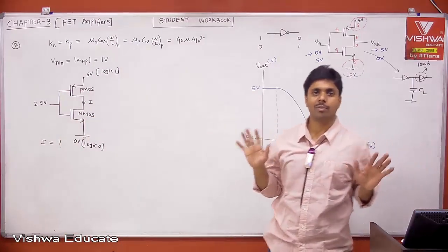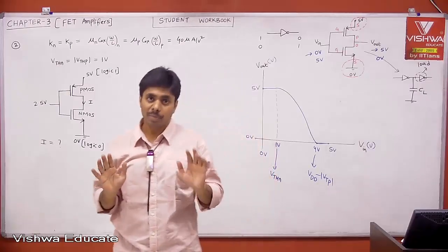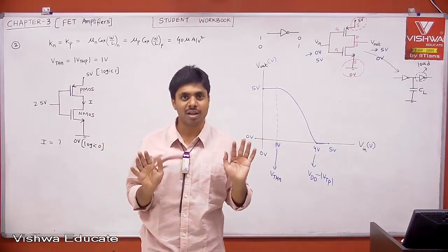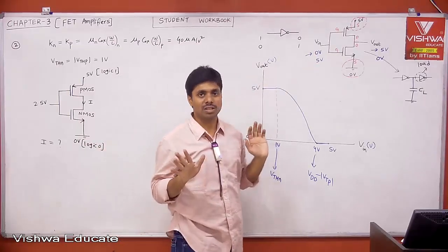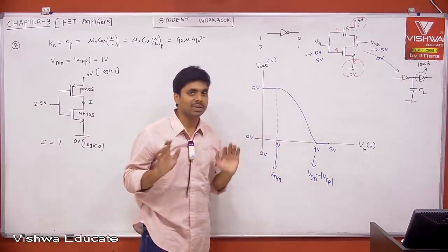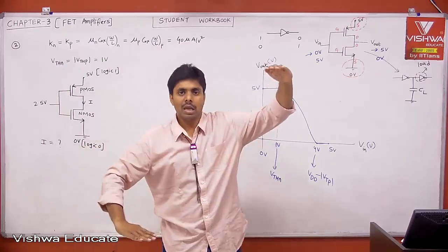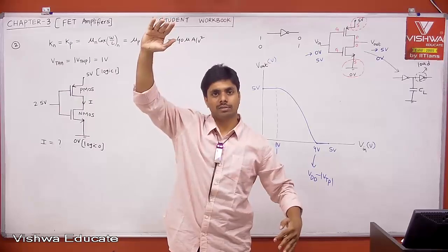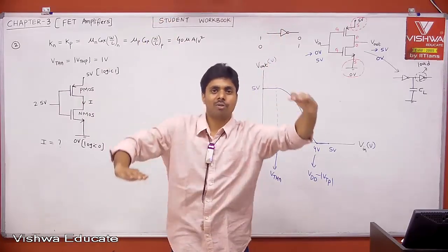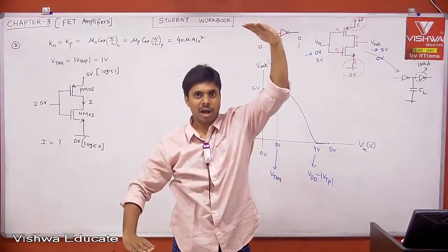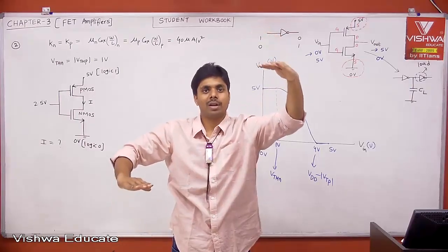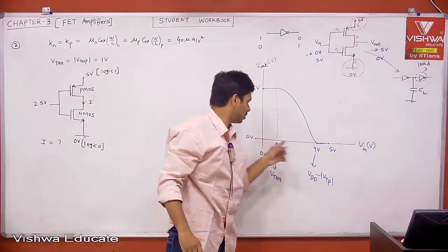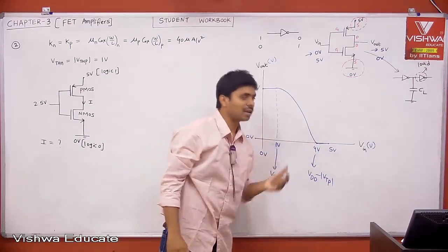I hope everybody understood it. I explained qualitatively, but there are quantitative problems we are going to solve later, meaning what's happening in between for different voltages. But remember, this is our transfer characteristics. Input is 0, output is 1. Input is 1, output is 0. When the input is changing, your output will change, but up to some 1 volt, the output will not change. From that point, it will change. But again, the output is saturated because that is our region. This is what people call noise margins.